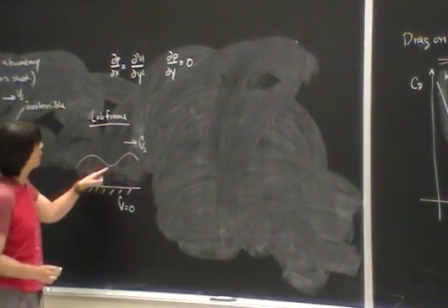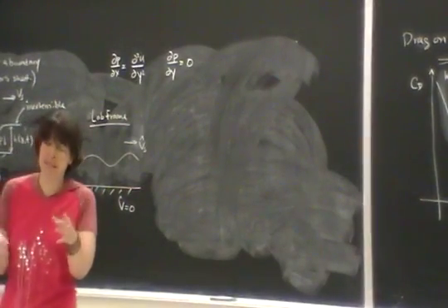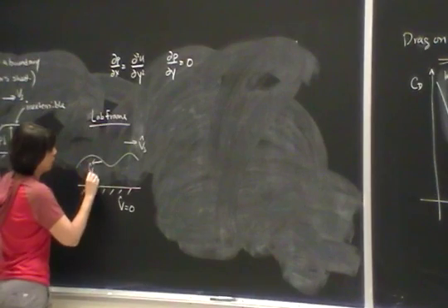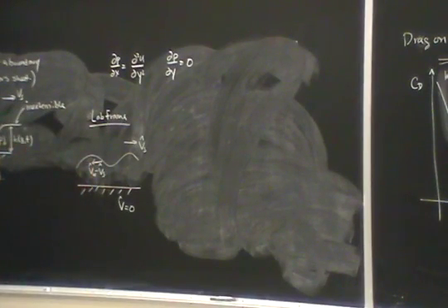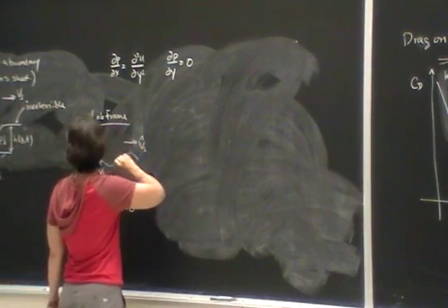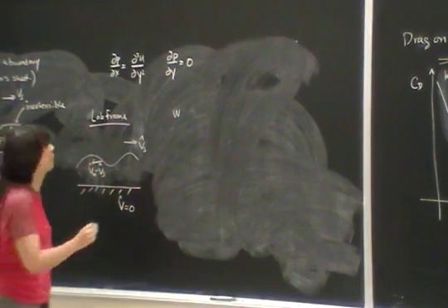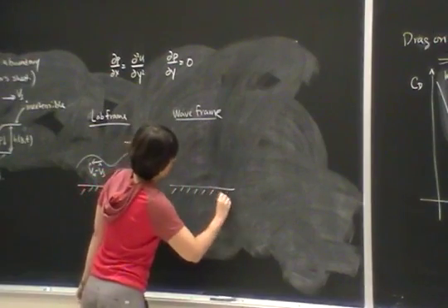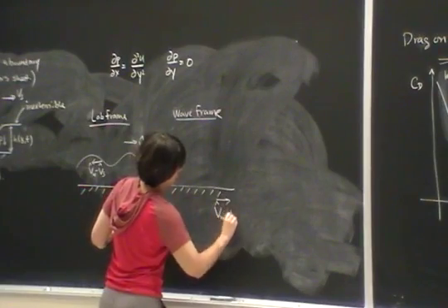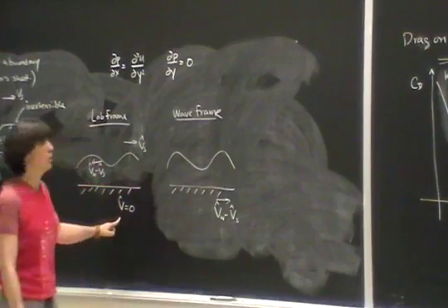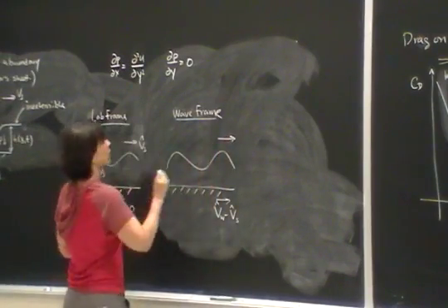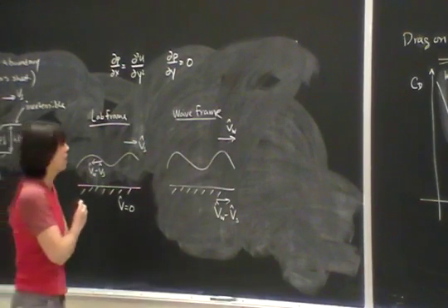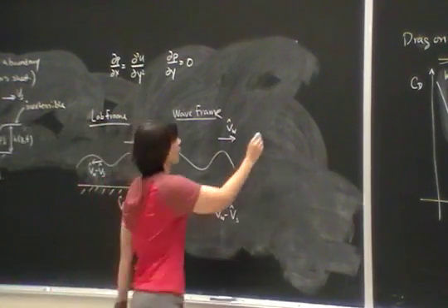And I have a wave velocity, which I measure in the frame of the snail. Imagine your snail is some kind of robot or device where you turn on a motor and it generates a wave moving at a certain speed, which means that there's going to be a wave speed that goes this way, which is going to be v wave minus v snail. Then, of course, you have to go into the wave frame. What I'd really like to do is make this boundary stationary, so I don't have to worry about it deforming. So in the wave frame, this now becomes v wave minus v snail. This thing is now not moving, so this has zero velocity, and then this guy goes in this direction at some velocity v wave. And then the last thing I'm going to do is normalize everything by v snail. So this is now dimensionless form.